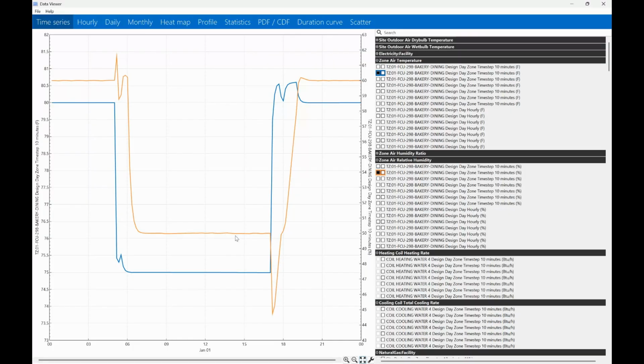So you'll notice that there's no mode switching on this, and that's because we have two independent systems. We have a cooling coil system and a heating coil system. So it doesn't have to mode switch. Whereas if we're talking about a DX coil system, which has to satisfy two different needs, sensible and latent.